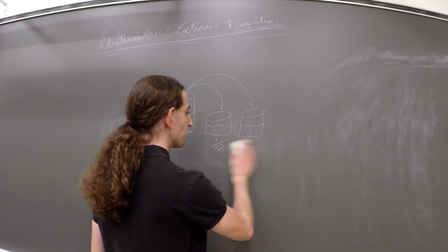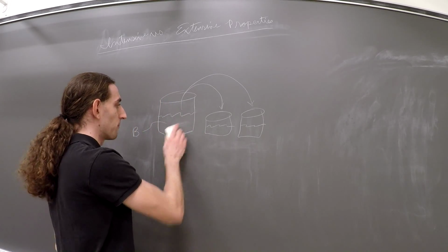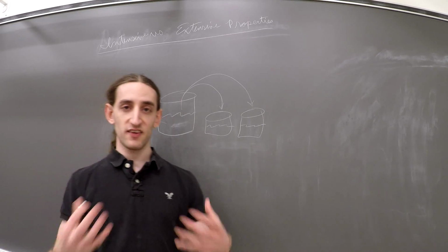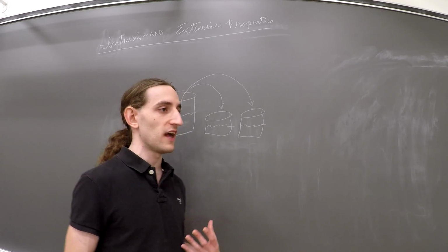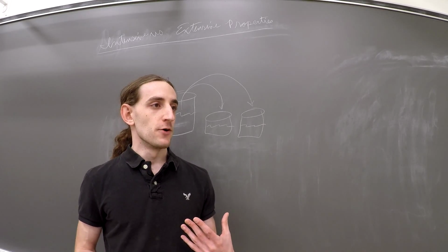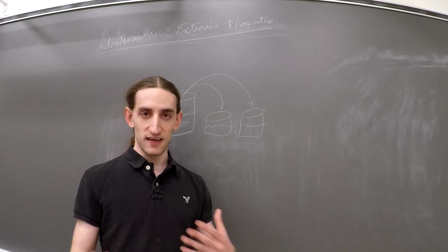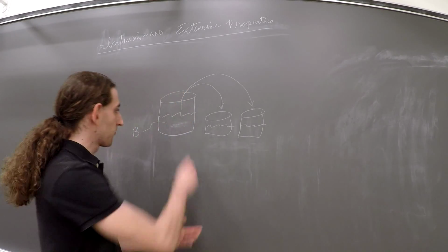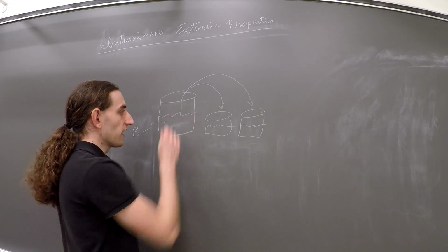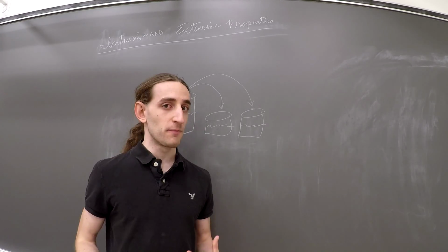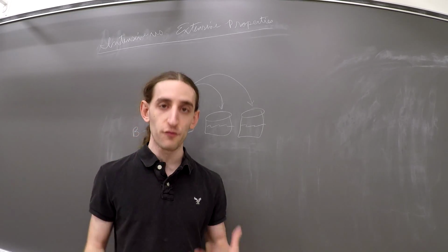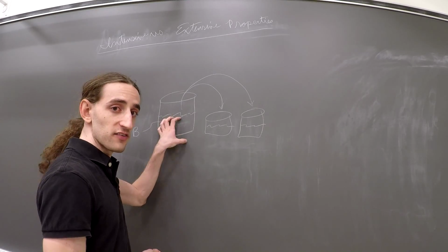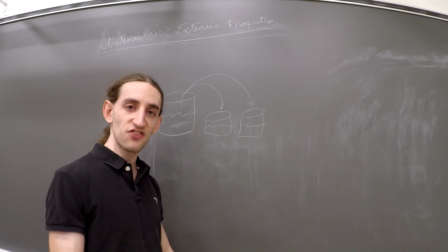So let's take a look at that. With intensive properties, these are properties that are intrinsic to the material you're analyzing. So examples are like maybe the density or the temperature, in the sense that throughout this domain, you're going to have the same amount of that property, provided that it's uniform, like that we have uniform density. So if you take like an entire system, intensive properties are not contingent upon the size or